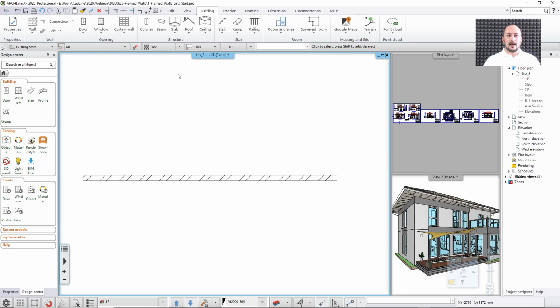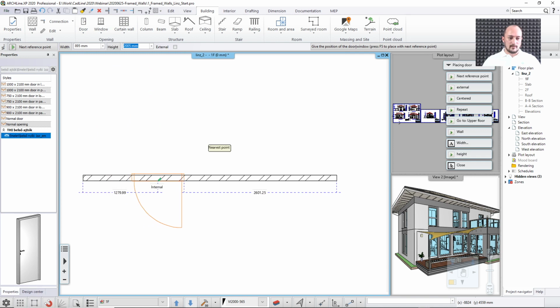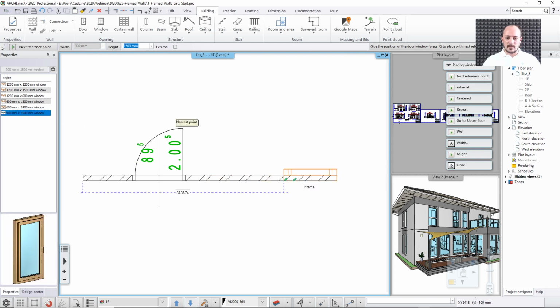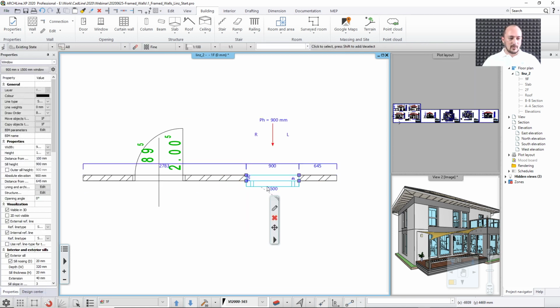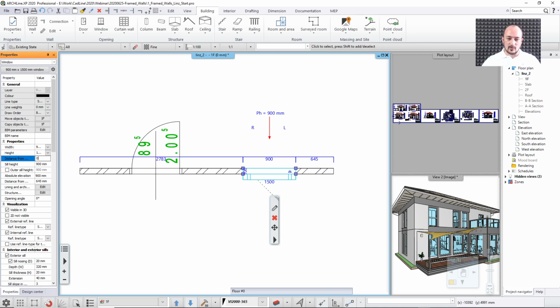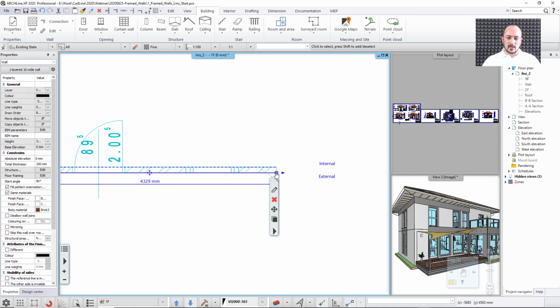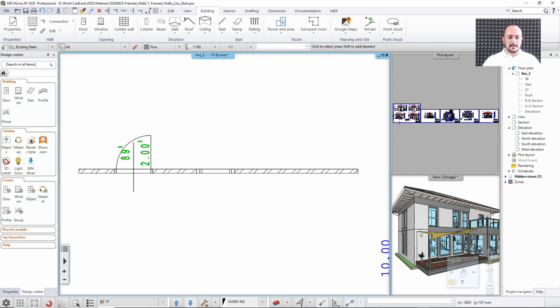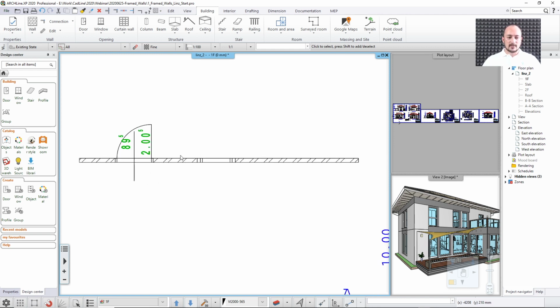so I will be able to see all the details around the door and around the window and above and below the window when I design this system. So for that purpose, I will place a door, for example, here. The opening direction is not that important, and I will place a window somewhere here. I will use a smaller one, something like this, a little bit thinner, and I will change its default distance from the wall line, on the left hand side. I can see that it should be 0 because now it is hosted in a partition wall. Let me change the length a little bit more so we can see the regular beams and columns later. And we have a door and the window, and let's go and set up the details.